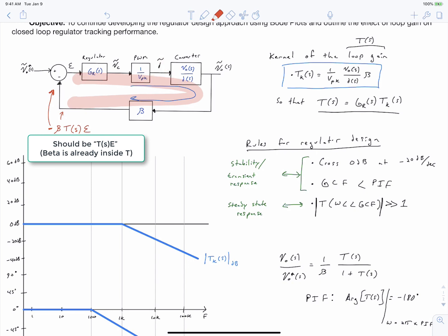And so one of the obscurities about this analysis is that we're only worried about the phase inversion frequency coinciding with the gain crossover frequency. So that means we're only worried about the phase inversion happening when the gain of our loop transfer function is unity. And that's because if we have a phase inversion at a much higher frequency than our gain crossover frequency, if we have a phase inversion somewhere way out here, the magnitude of our loop gain is so low that it does not matter that it gets added back in up here.